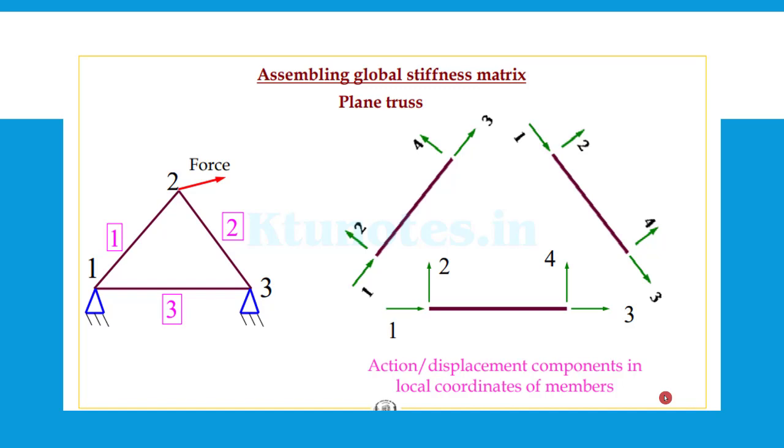So, the global coordinate stiffness matrix will be the corresponding displacements in the element, expressed at the global coordinate level. If we have three members, each member will have its own element coordinate. By the rotation matrix, we convert these to the single global coordinate displacements, and then we can just add element 1, element 2 plus element 3, which are in the global coordinate, to get the total stiffness and the other values at the global coordinate level. To make it clear, we will see a problem.